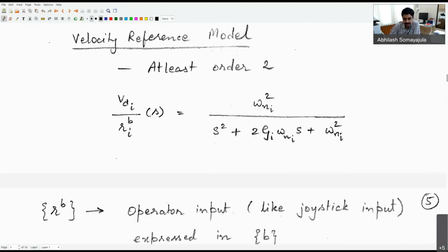So you would have a similar sort of filter for each of the different things which you want to control. If you have a 3 degree of freedom system, you might have one for the velocities in surge and sway, or in the north and the east, and then the heading rate could be another.